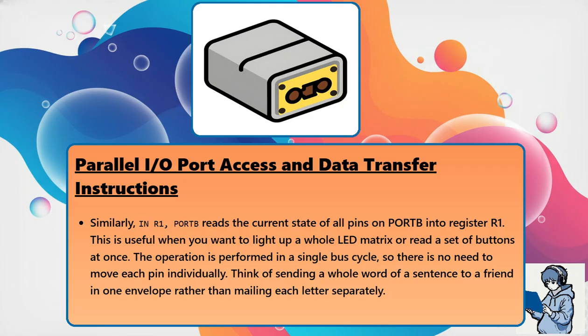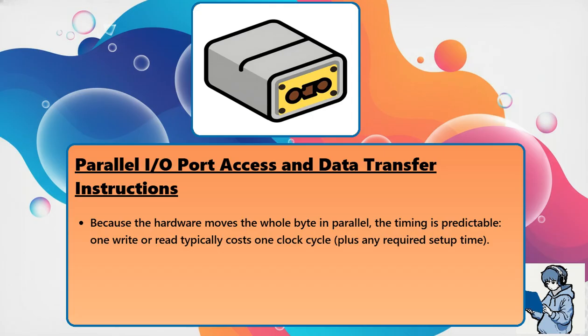This is useful when you want to light up a whole LED matrix or read a set of buttons at once. The operation is performed in a single bus cycle, so there is no need to move each pin individually. Think of sending a whole word of a sentence to a friend in one envelope rather than mailing each letter separately. Because the hardware moves the whole byte in parallel, the timing is predictable. One write or read typically costs one clock cycle plus any required setup time.